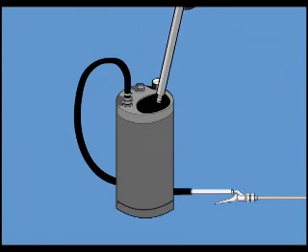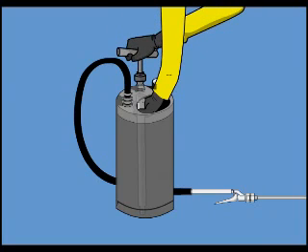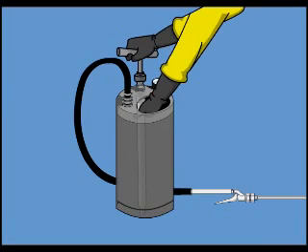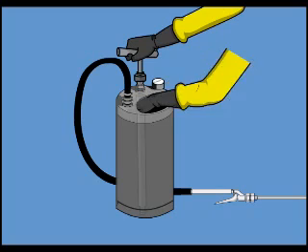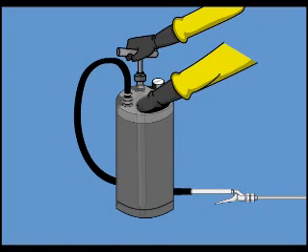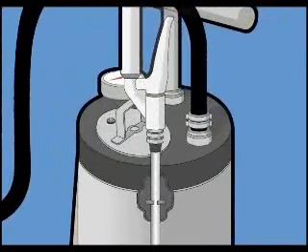Reassemble the pump. Check the gasket is in place on the pump cylinder. Then hold the pump cylinder inside the tank with the threaded part through the opening in the top of the tank. Insert the pump plunger into the cylinder. Turn the plunger cap counterclockwise on the cylinder to ensure the threads match. Then screw the cap on and tighten. Check the relief valve is seated correctly and air does not escape until maximum pressure is reached.